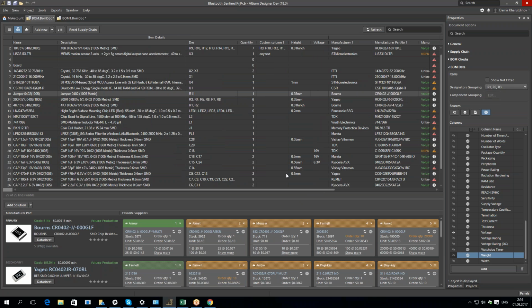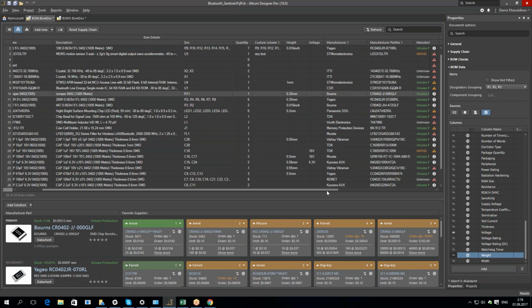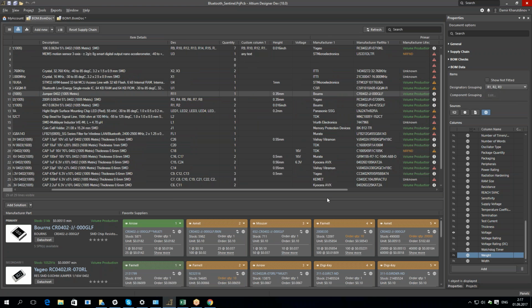The second, quite interesting, is validation of your BOM. You can load parsed data and compare it with the data you have in your schematic, and try to identify those cases when you have linked the wrong MPN or you have typed the wrong parameters in your schematic component. Practically, you can show the value column from the design and the value column from the cloud and see the difference in the values. If there is a difference, that might be something to investigate.